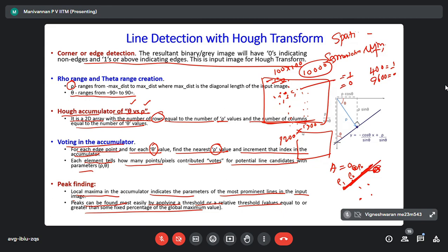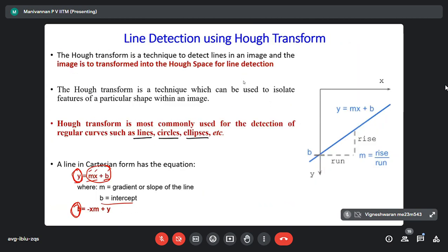Image processing has 6 steps to detect an object. That also you have to do in real time. Please know that. How? Minimum frames are 20 frames per second that a video camera has to take. Already we saw the relationship of what the minimum speed should be.